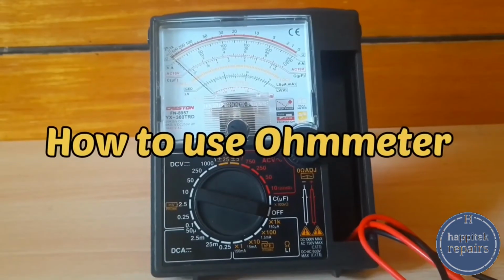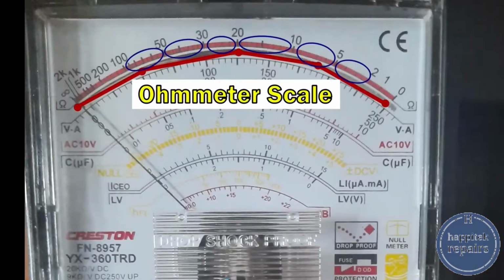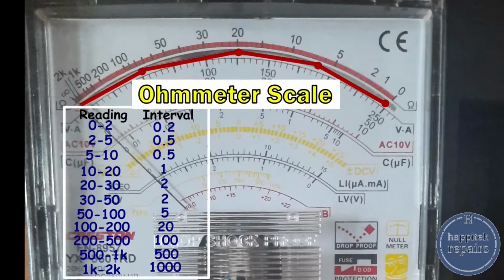Move on to how to use the ohmmeter. The first thing we need to know when using the ohmmeter is to interpret the ohmmeter scale. See, there are gaps in between which do not have indicated numbers, and it makes a number from 0 to infinity. Scale 0 to 2, the interval is 0.2. 2 to 5, we have 0.5. 5 to 10 is 0.5. 10 to 20, the interval is 1.